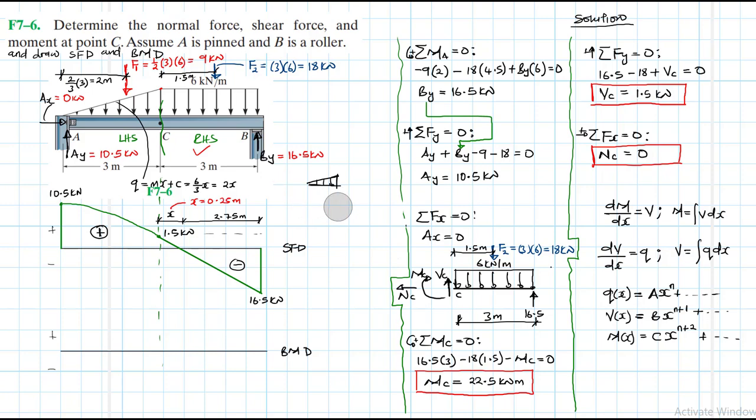If I write this, let me write the support. I'll have the support there, we found a 10.5. This is our A. This point here we say this is our Q, which we already found, and Q is equal to 2x. Then I'll have an equivalent force of F there, and then this distance here is just equal to x. Then I have my shear V, and then I have my moment M.